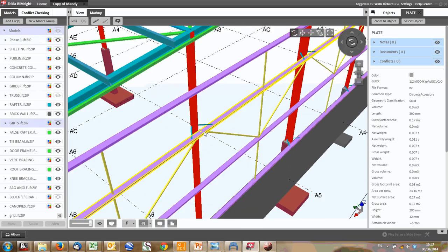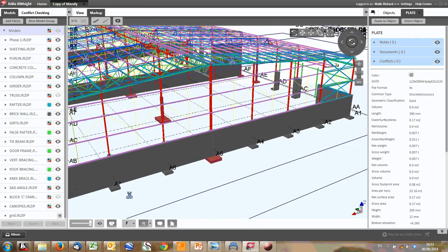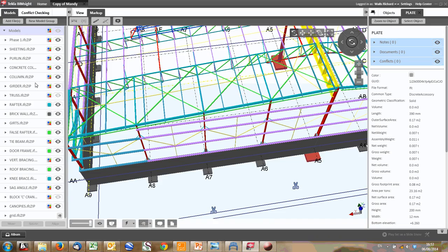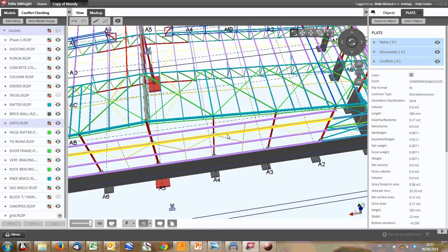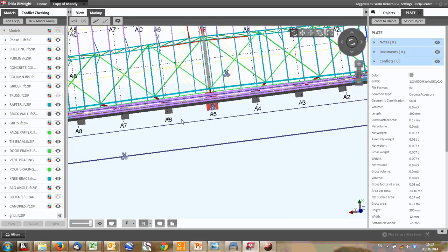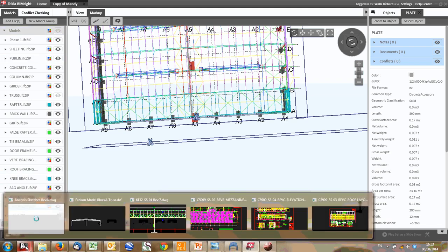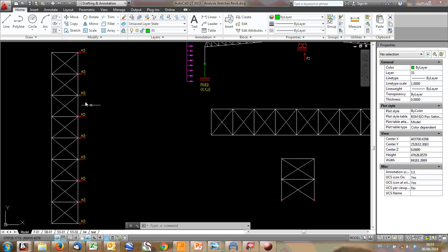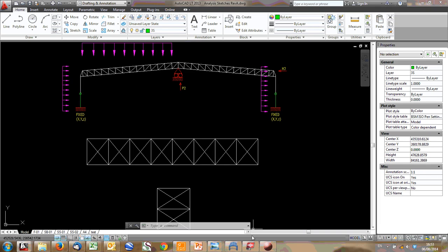Now, let's have a look at the top. Where does this top load go? So the wind comes along horizontally. We need to get this load now into these foundations. And the way we do that is with roof bracing. We can provide a lot of stiffness to this entire gable face with roof bracing, whereby a load coming along hits it, and this is a giant truss all the way along the top. So if we go back to our model, there we go, giant brace all the way along the top. In the same way that we brace the trusses, we're bracing our gable face.